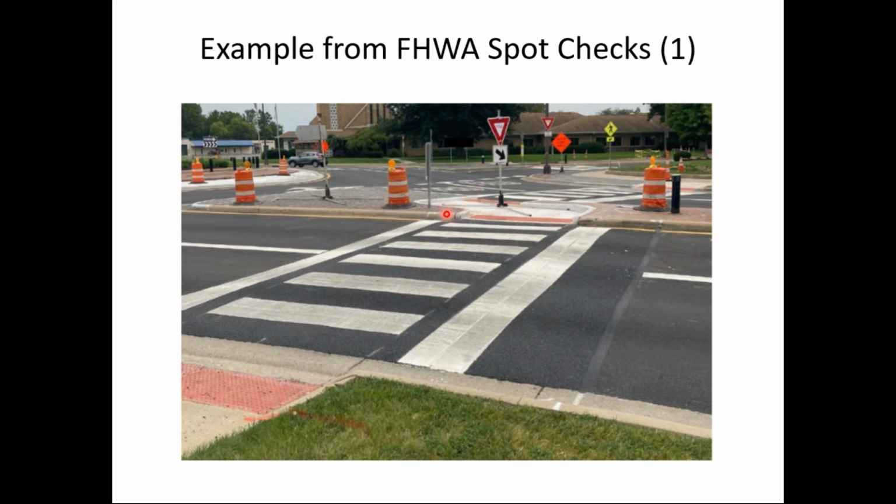It's outside the scope of this class, but these Z crossings, as they're called, are very popular. Usually the idea is that when the pedestrian crosses the street in the direction we're looking here, they would turn to the right, and the pathway would take them a little bit to the right so that as they're walking, they can check for oncoming traffic and they can see the traffic stream they're about to cross. Here, they're walking away from the traffic stream they're about to cross, so they sort of have their back to traffic. But anyway, the key issue here is accessibility of that refuge island.